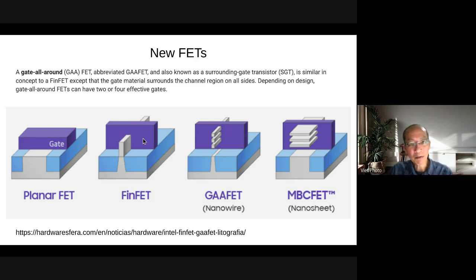One here, left, right, and top. This one has that all around, and they have not only one doping region, they have three. When they do that, you can imagine the current will be even higher, because each region is equivalent to one transistor. If you can put three at the same time, it means you have three transistors in parallel, which increases the current and the performance.